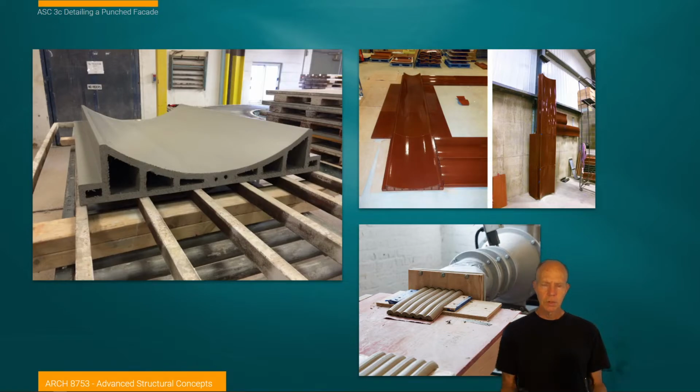And in this case it's also glazed, which means that they fire it once to make it into the semi-ceramic terracotta material that it is. They coat it with a glazing system, and then they fire it again. And that's important to note, because when we glaze tiles to create that color, we're going through another firing process, and that increases the amount of embodied carbon that the product has. So on the bottom next to me here, that's just a close-up of what an actual extrusion die would look like. So here we're pushing clay through a shape that creates that kind of pattern that we see there.